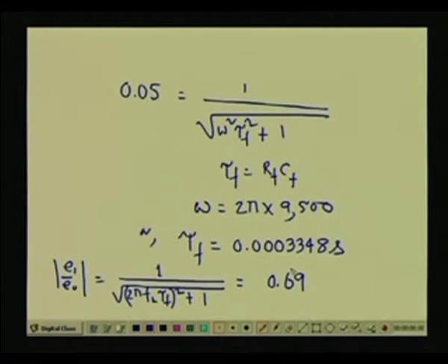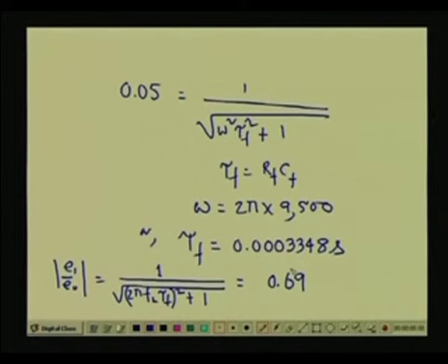Thus, we see that the high frequency portions of the Xi will be distorted considerably. Xi is the movement of our LVDT core, so that will be distorted considerably. The inference is that this type of first order section will not be suitable for this application. So, let us take a second order section.